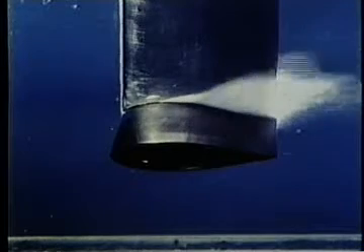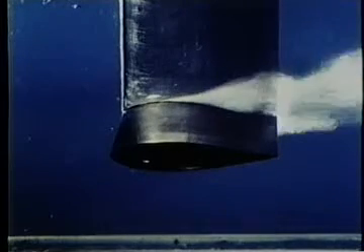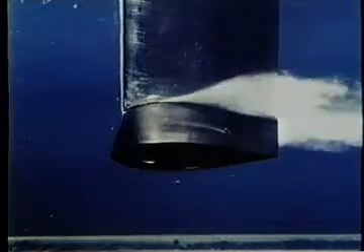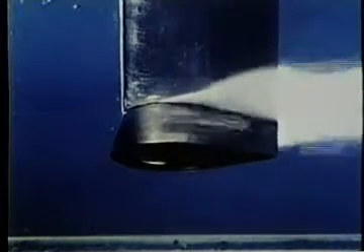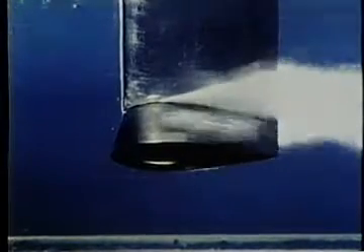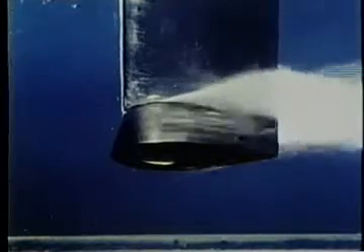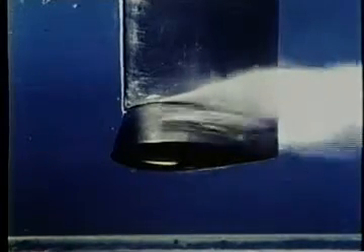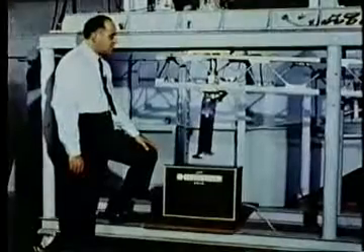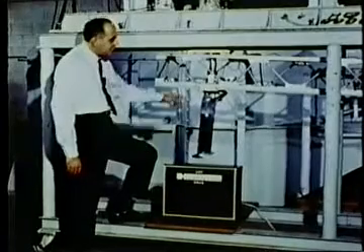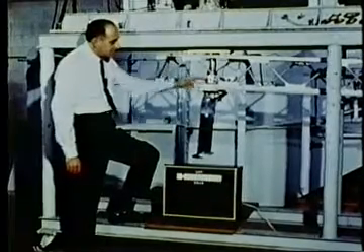What happens to a machine when it begins to cavitate, and how does performance vary with increasing extent of cavitation? Since hydrofoil sections make up so many different types of machines, pumps, turbines, propellers, propeller shaft struts, mixers, we can illustrate what happens to all such machines by studying the forces on the hydrofoil section itself. We have suspended the first hydrofoil model from force gauges, which show us lift and drag on these scales.